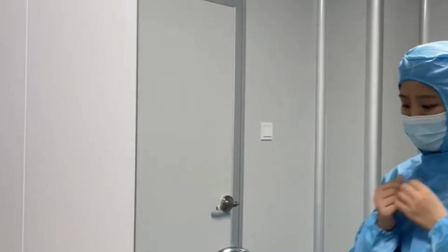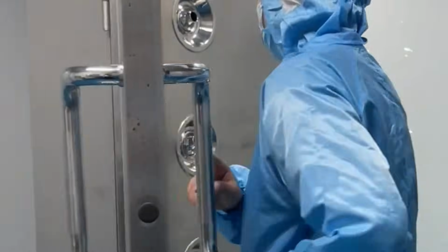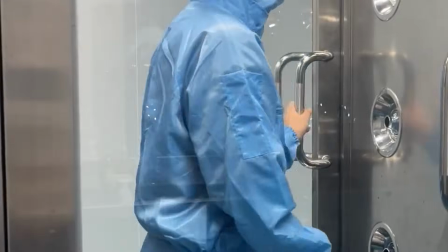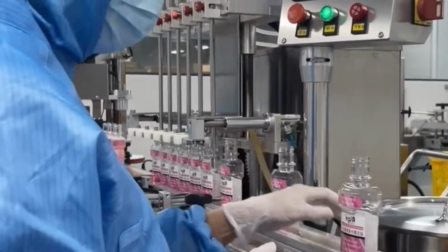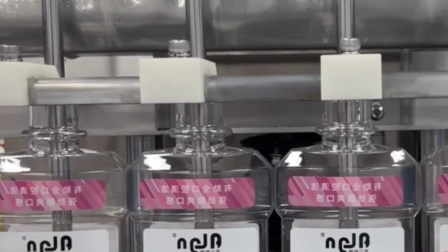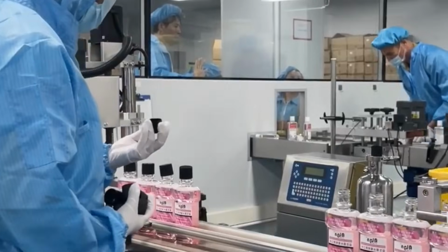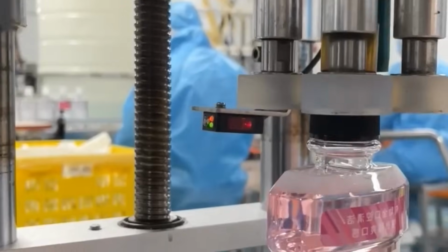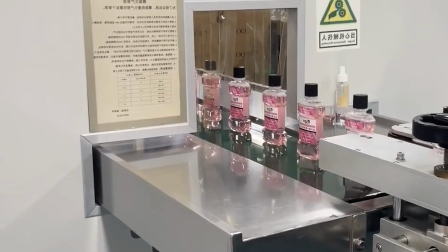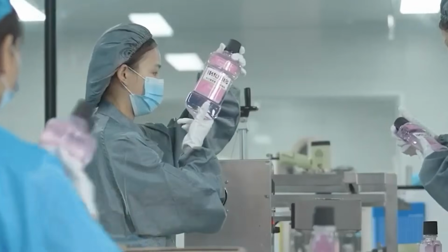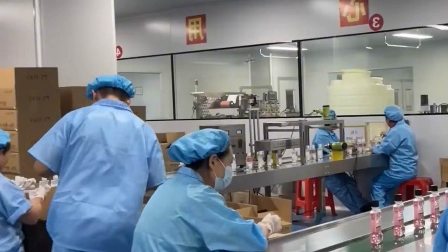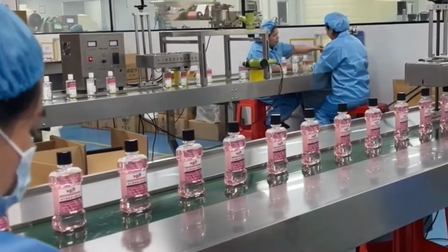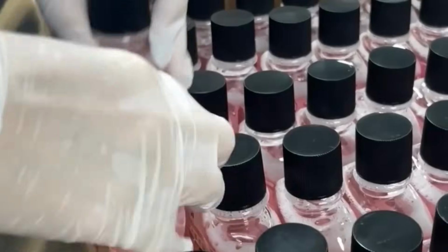Alcohol, when used as a solvent and preservative, is added next. Ethanol is transferred from explosion-proof storage tanks through stainless steel piping. The addition is performed under closed-loop nitrogen-blanketed conditions to minimize evaporation. Flow rate is monitored by mass flow meters, and volume is logged digitally for each batch. Final ethanol concentration typically ranges from 15 to 27% in alcohol-based formulations.